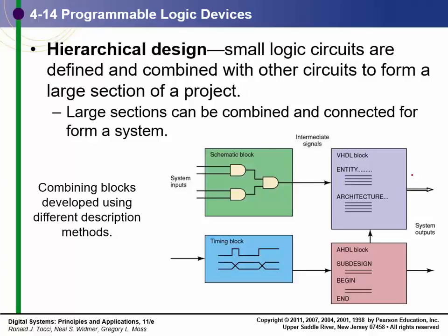We can use different design techniques for different parts. It might be easier, if you're going to be interfacing the memory, to work on the timing pattern and tell the software what the timing pattern has to be to talk to that. It may be easier for this group over here to draw schematics. This group over here is going to be working in VHDL because you're doing math processing and you want to do it at a very high level. You want to write something, use that there.